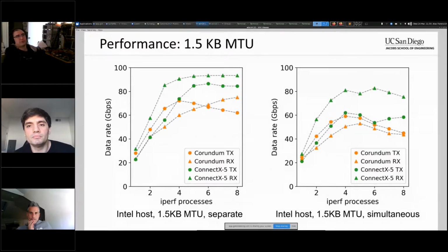Well, from my point of view, the whole point of Corundum is the fact that you can go in and make modifications to it. And as soon as you spin an ASIC, you lose that capability because you have a fixed function thing. It just means that for the type of stuff we're doing at UCSD, it's not something we're interested in. But you could certainly do that if you wanted to, say, just use Corundum as a host interface and build some crazy packet processing SmartNIC kind of solution, and just use Corundum as the host interface for that, and then spin an ASIC. That's certainly something that's doable.